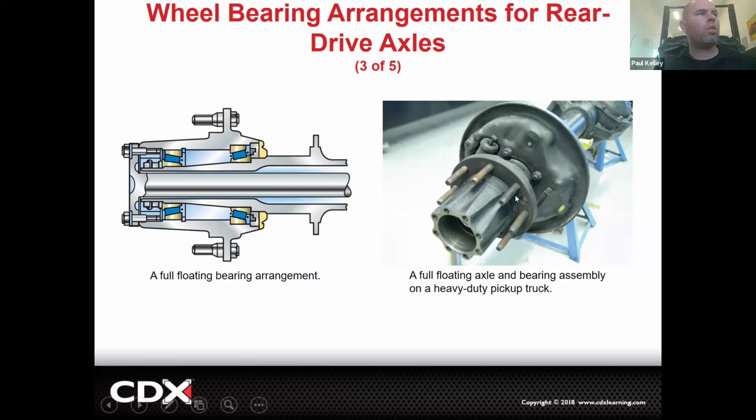Makes sense. All the weight is on this hub, and all the hub is on these bearings, and all the bearing support is on the whole big axle tube, the whole housing. Much stronger. The negative is you need a set preload on these bearings. So if you ever get into something big like this, you don't just get to yank this apart. You have to actually pull the axle all the way out, the 8 bolts. There's an axle gasket right there, so now you have to buy an axle gasket.